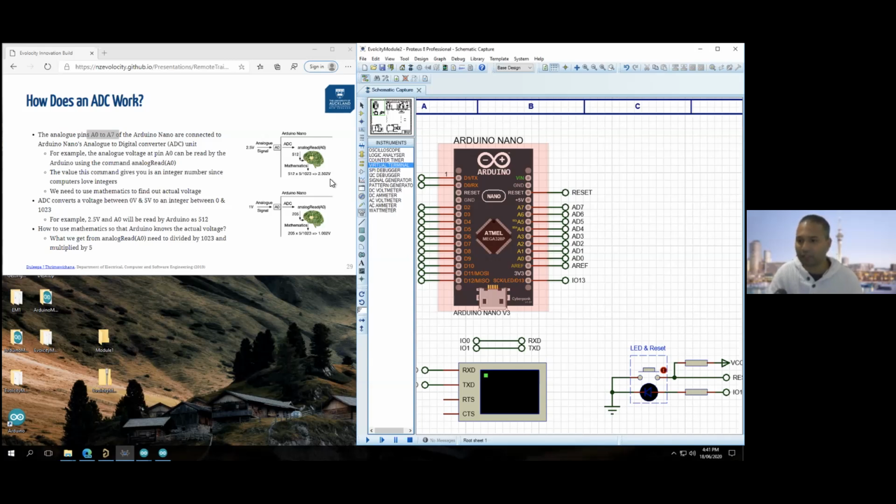So that's why when you go buy an expensive music system or expensive headphones, they have more and more bits to do this. So the more bits you have, the smaller that error would be. In this case, we have 10 bits, which gives a certain amount of error. But if I had 20 bits, it'll be an even smaller error. So that's why you pay the price in terms of how many bits you have in your analog to digital or digital to analog conversion.